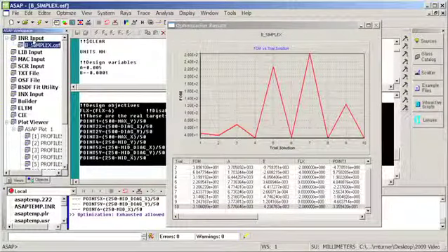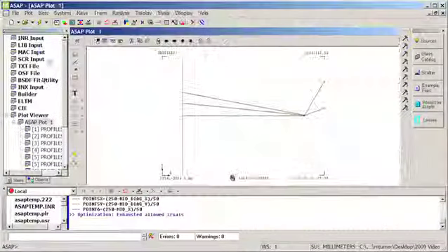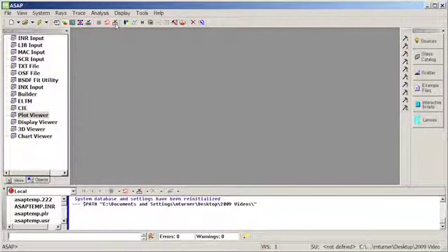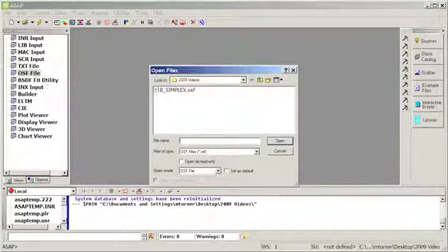Okay. And now what I'm going to do is close my current input. Normally this would happen when maybe I'd reached the end of the day and I was stopping my work for tonight and would come back in tomorrow. But rather than exiting ASAP, I'm simply going to close all my files and restart my ASAP kernel again to let everything be fresh. You'll now notice in the ASAP workspace there's an additional type of ASAP file called the OSF file. So what I'm going to do is just come over here and open the existing OSF file.